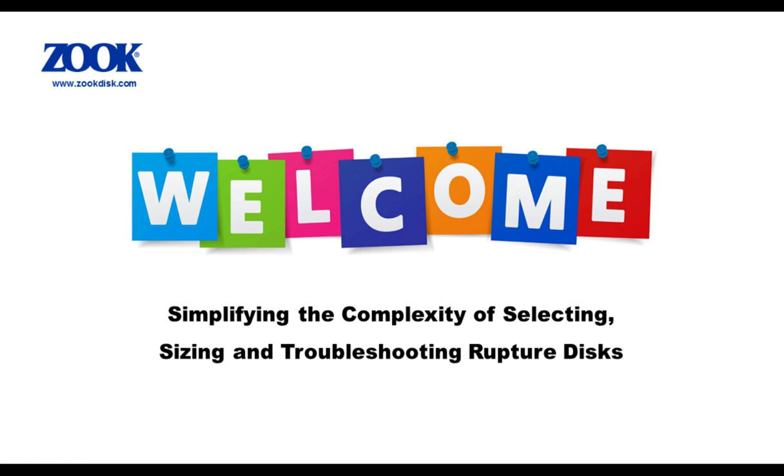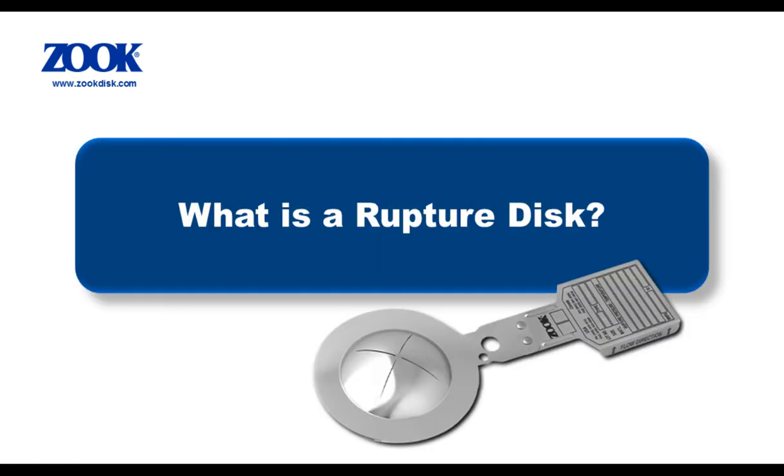Before we start to discuss what you need to know about selection, sizing, and troubleshooting, I want to provide a quick introduction to rupture disks. First off, what is a rupture disk? At its simplest, a rupture disk is a safety device. It's actually a pressure relief safety device, one that is typically custom designed to protect plant, personnel, and equipment from unplanned or unexpected overpressure. That's a fancy way of saying it's designed to stop things from blowing up. It's generally a one-time use, thin diaphragm designed to rupture or burst at a designated pressure.